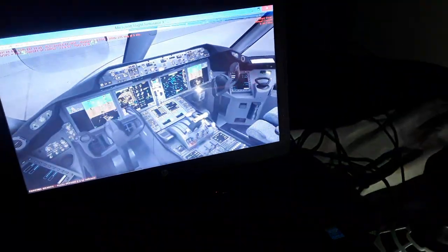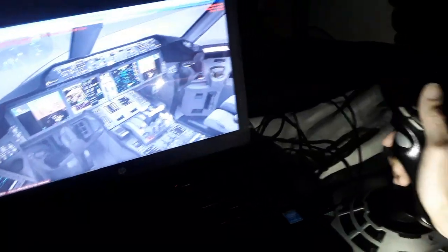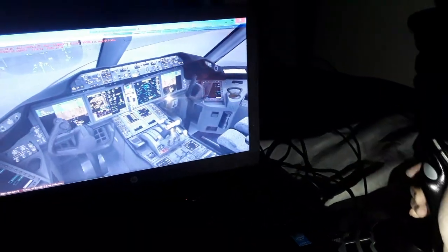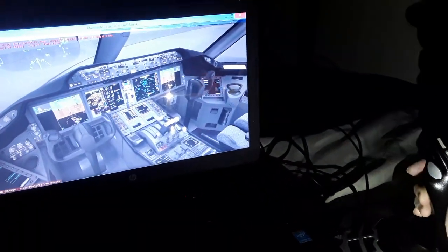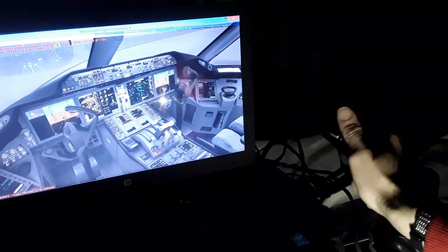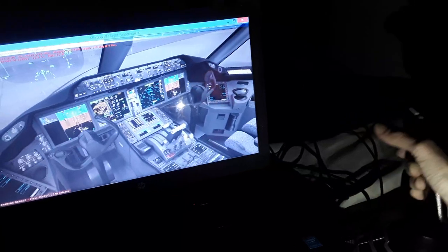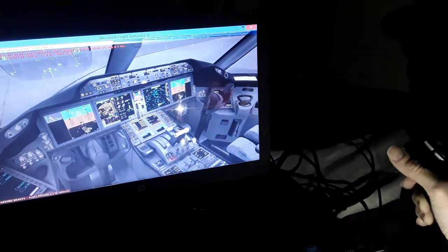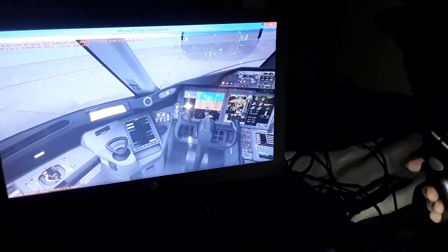So I will show you the flight controls also, how you use them in flight, how to use the side stick to input over here, the yoke of the Boeing 787. So you can use the elevator for climb and descent, also the ailerons and the spoilers, bank rolls over here, and the rudder pedals make coordinated turns in flight, nose wheel steering on the ground, and toe brakes.